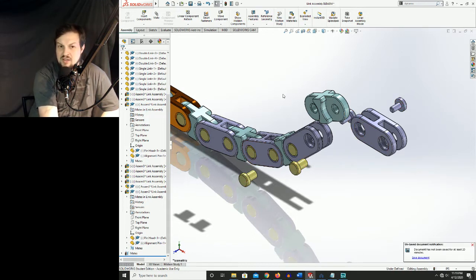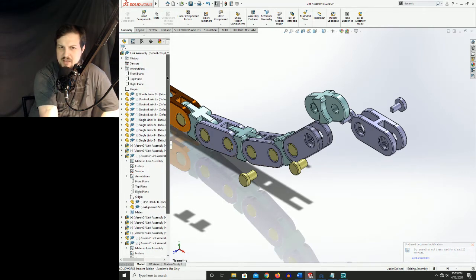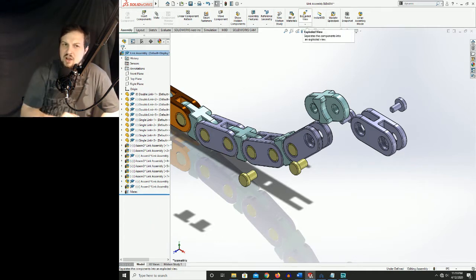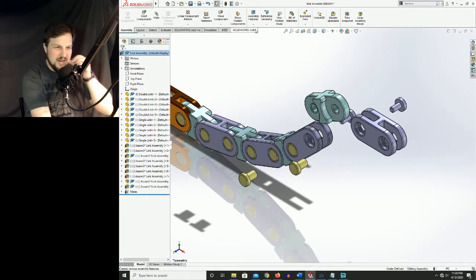Uh-oh. Now you can see another problem. I went too far. I exited my exploded view, so I'm no longer in that exploded view. Okay? So if you exit your exploded view and you hit this button right here, it's going to start a second exploded view. We don't want to start a second exploded view. The more you have, they just kind of pile up and you never get anywhere, and every time you exit one, all your stuff disappears, and that's bad.